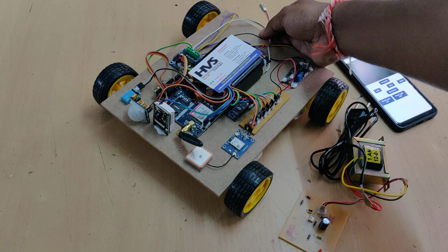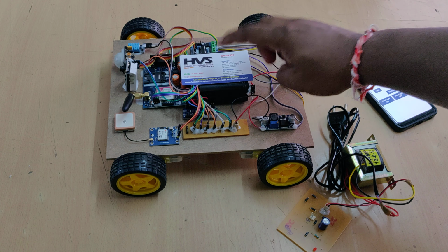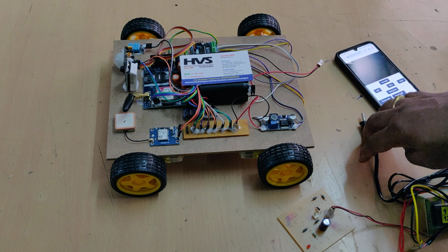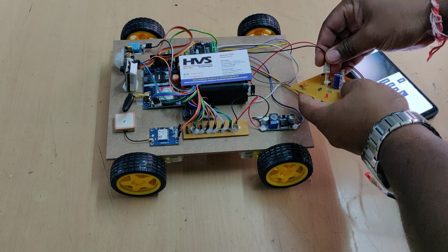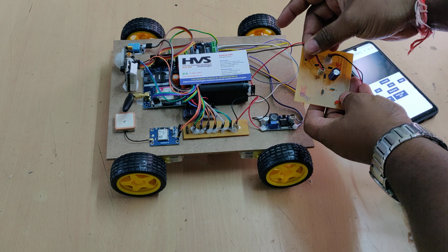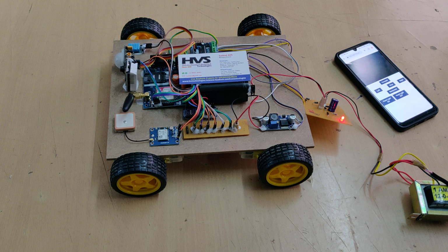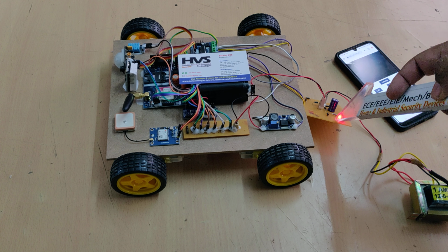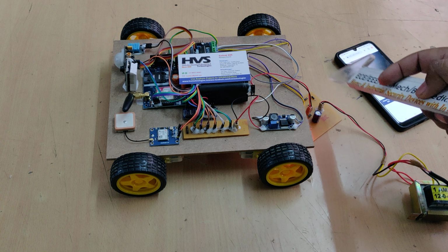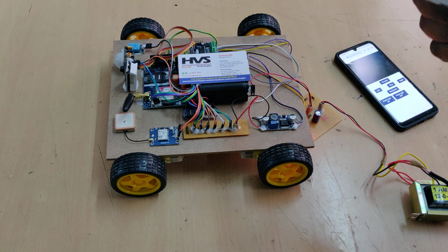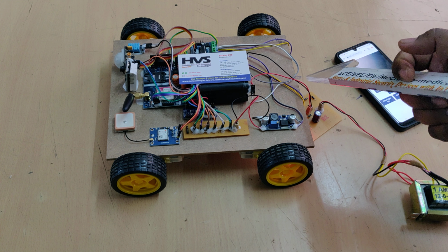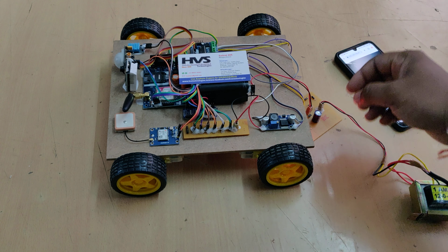Before switching on, the main thing is we should keep this battery fully charged. For that purpose we have provided the battery charger. Connect the battery at these B slots and switch on the power supply for the transformer. The transformer will step down the 230 volts AC to 12 volts AC, and this regulated power supply board will convert that AC to pure DC voltage. The charging time is 6 hours minimum, 8 hours maximum, as we are using a timing based charger.